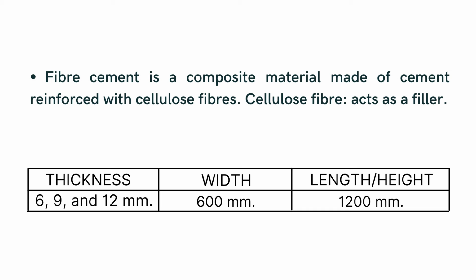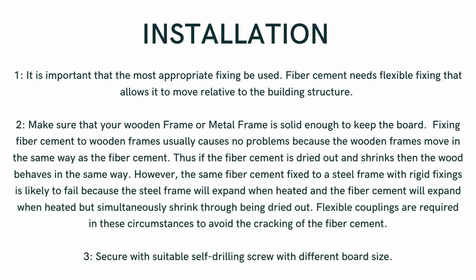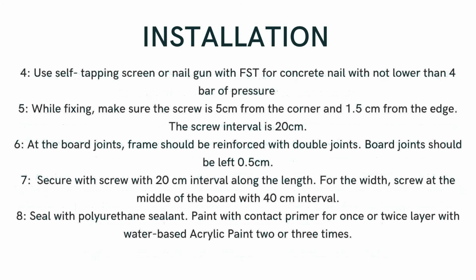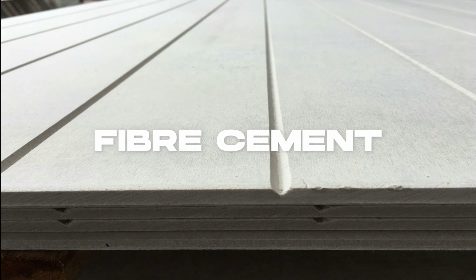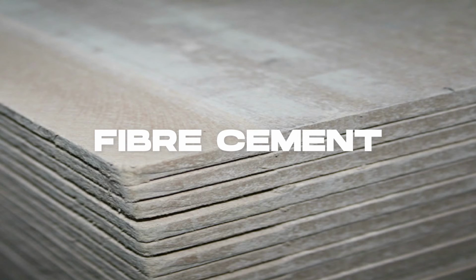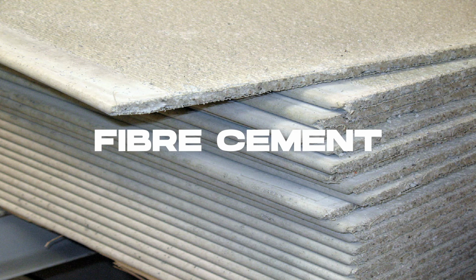A color that is available is usually gray, but it can be painted. A property of fiber cement is that it is durable against weather conditions and resistant to fire. Fiber cement is a composite material made of cement reinforced with cellulose fibers. Cellulose fiber thickness is 6, 9, and 12 millimeters. Width is 600 millimeters. Length or height is 1,200 millimeters. Installation. Brands available.